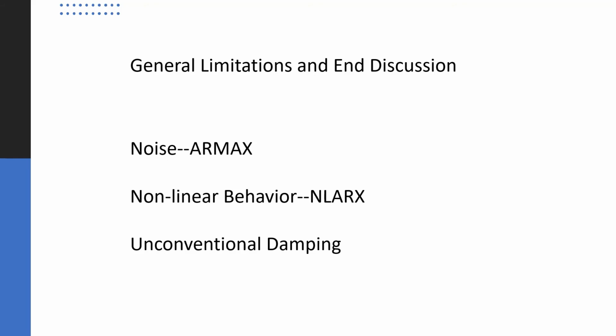Besides, the structural behavior in an earthquake is very critical in structural monitoring. During earthquake activity, the building will have nonlinear structural behavior. The seismic resistance members will yield during the earthquake. And ARX cannot analyze the nonlinear behavior of the structure. As a result, we can use NLARX instead, or other techniques which can analyze the nonlinear behavior of structures.